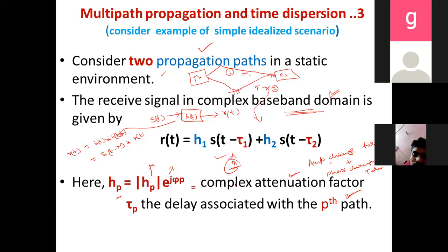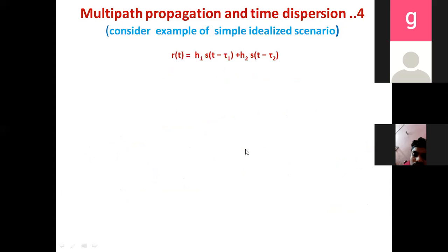The net effect is that the signal received at the receiver changes its amplitude as well as its phase because of several effects, mainly the time delay spread or the Doppler effect. So let me discuss a small example, time delay spread.